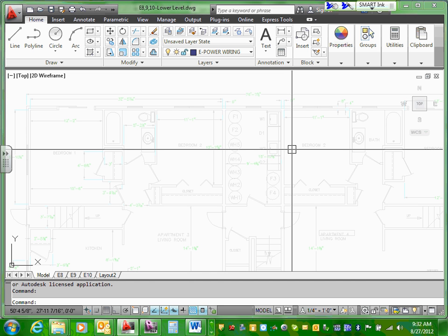Xref? Yeah. Okay, can you do me a favor? Xref directly from the site. I think you did them from your C drive, then you copied it. It doesn't work. Alright. You're just gonna go do them again. Just get rid of them and then bring them in from that site, so he can see them. That's all. See what it says there? It says C. Yeah. It's referencing it to the C. Right. So that's easy to fix. Okay, we're cool.